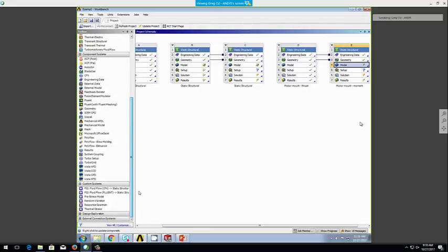So first of all, aircraft under load or at rest is under load factor of 1. So what's the load factor? The load factor is the number of G's that you're pulling. So N is equal to the load over the weight of the aircraft.